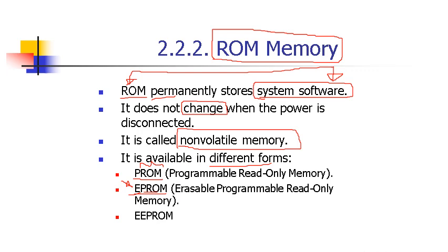Okay, and this kind of ROM, EPROM, they used to shine ultraviolet for 20 minutes to erase the data inside the PROM and reprogram it, which requires a setup for a UV ultraviolet source, concentrating the light and letting the light go through a glass window inside your memory device to erase the data. And this was not easy to deal with.